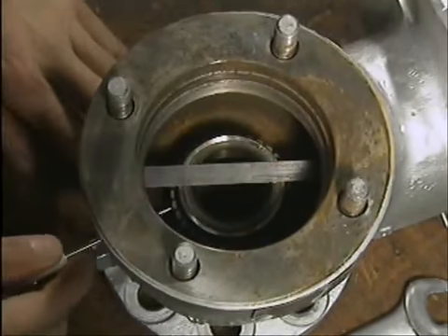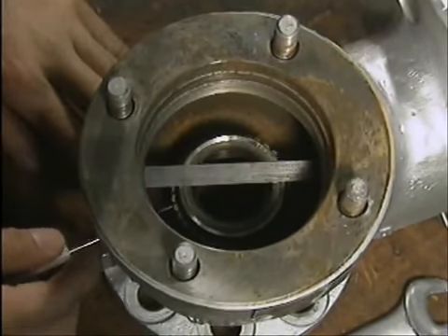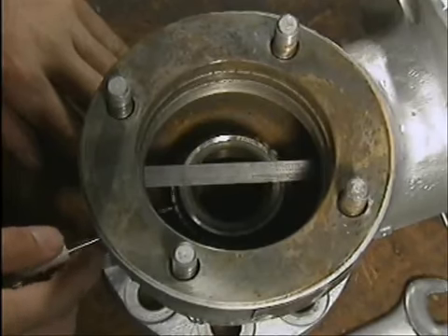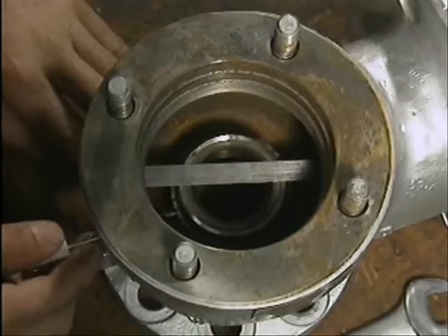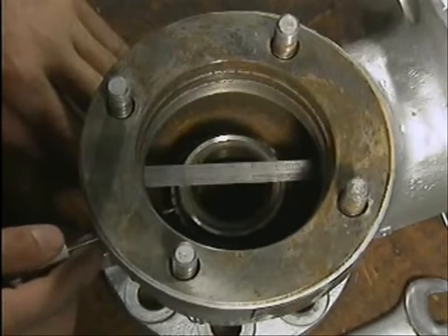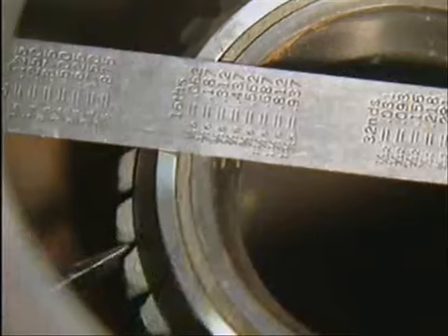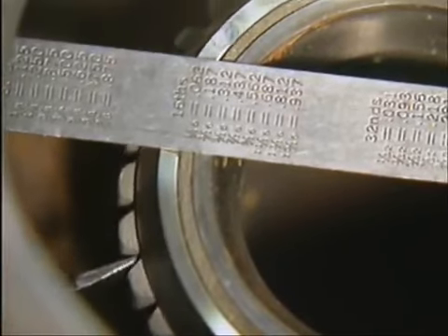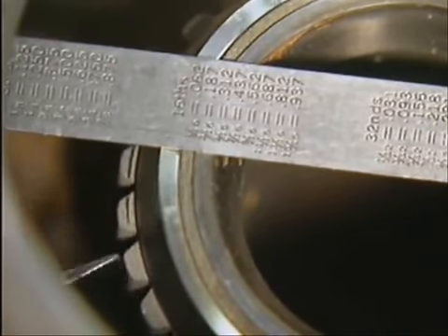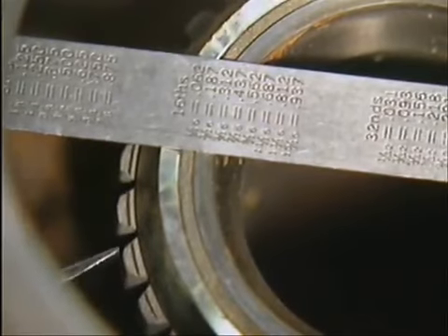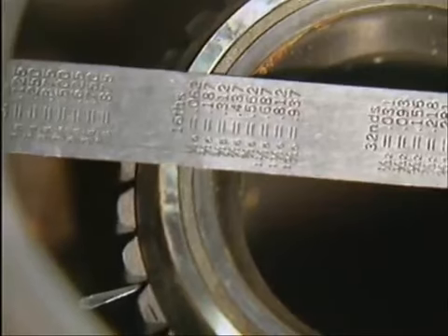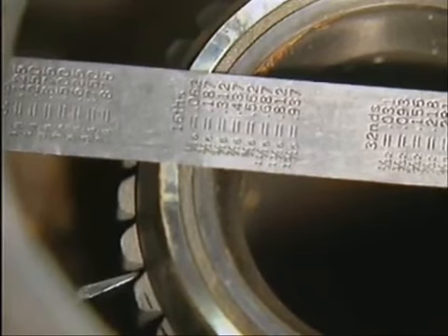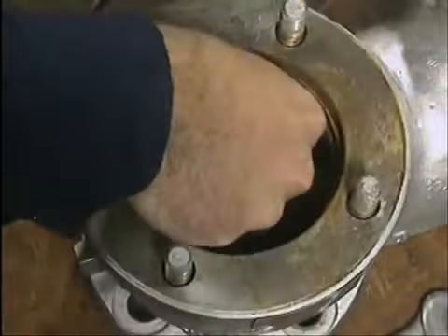Insert a screwdriver through the lower locking pin hole and unscrew the ring by turning each notch past the pinhole until the ring is flush against the rigid rule that was placed on the valve seat to take the measurement. Count each notch as it moves past the pinhole while the ring turns. Write down the total number of notches that you counted. This number will be used to install the ring correctly when the valve is reassembled.